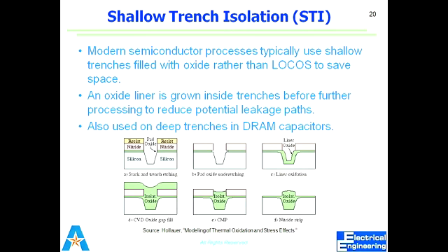After under etching we grow the oxide layer here, and after growing, what we do? CVD, chemical vapor deposition of oxide. So here we don't grow, here we deposit. If we need a thicker layer, we can deposit that oxide layer, and then chemical polishing, and then we remove our nitride.